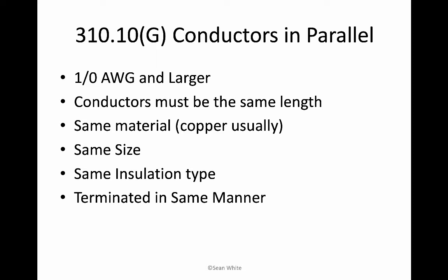And another reason is with alternating current, there is something called the skin effect. When you get to large amounts of power going across a wire, you start worrying about the skin effect. And that's all about electrons trying to flow on the outer part of the conductor instead of the middle part.